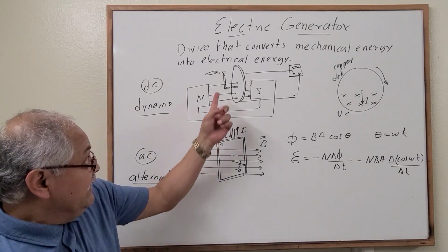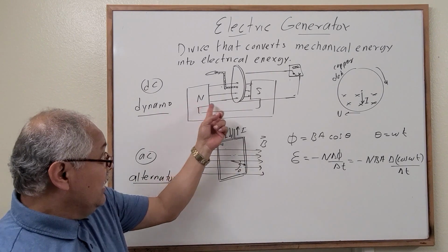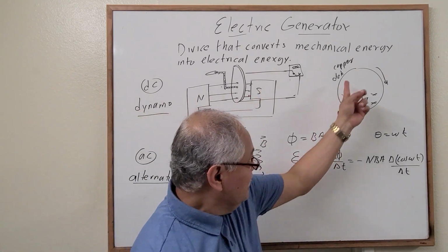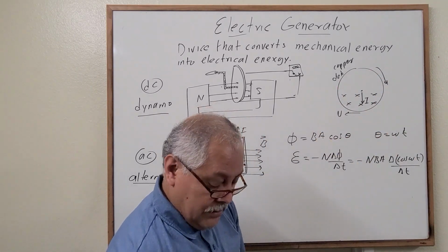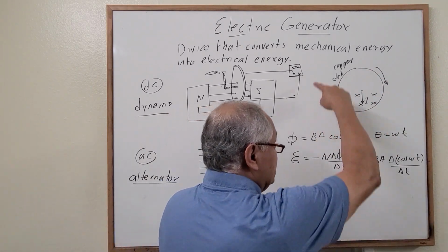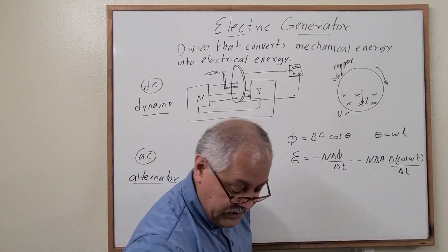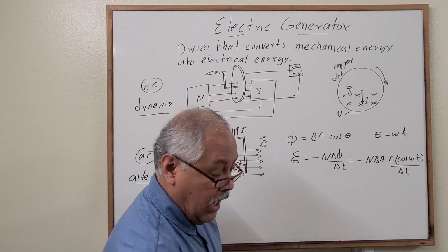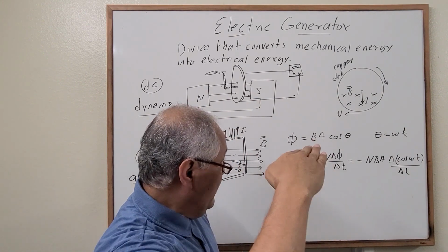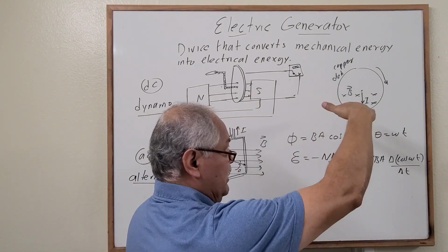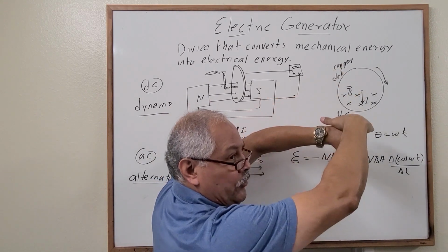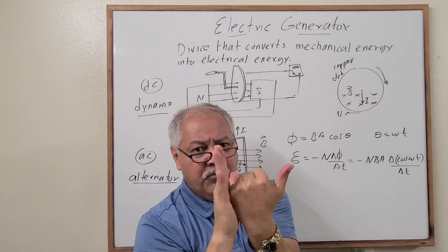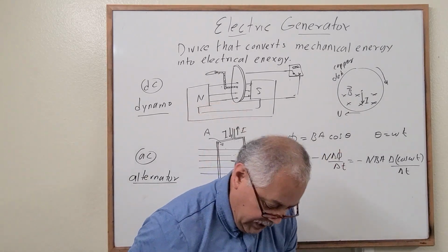In this case, we have a disk that's rotating inside of a constant magnetic field. Because this is a conductor, imagine it's rotating in this direction, and imagine the magnetic field is going into the wall. So we have the magnetic field into the wall, we have the velocity, so we have a force going down. Remember, we use the right hand rule. This is the magnetic field, this is the velocity, the force is perpendicular to this plane. Okay, perfect.